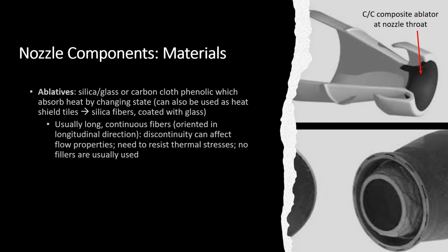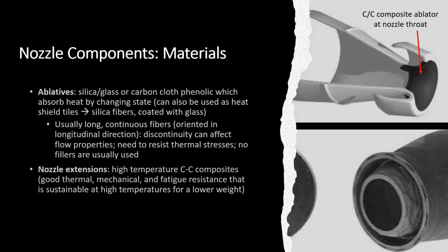Overall, most of these components are structural parts that resist tensile, compressive, and bending stresses or moments, so mainly long-oriented and continuous fibers are used, although continuous fibers can be used for impact and corrosion resistance coating. This would eliminate many discontinuous composite manufacturing possibilities like spray-ups. And for the same reason, fillers are not often used, as to not compromise the integrity of the structure, especially when the goal is to maximize the material strength and modulus.